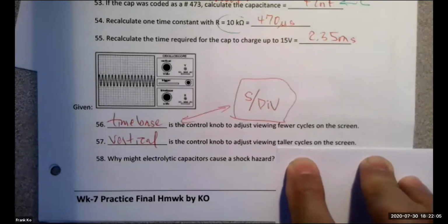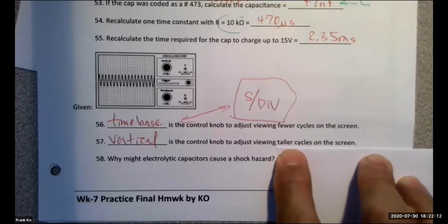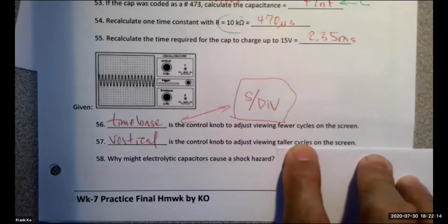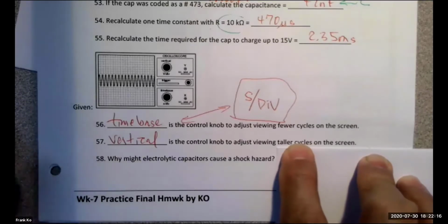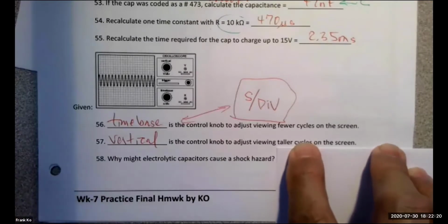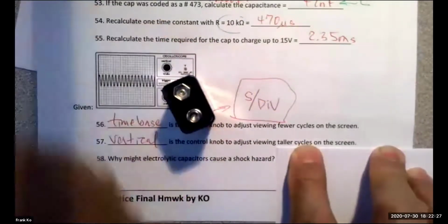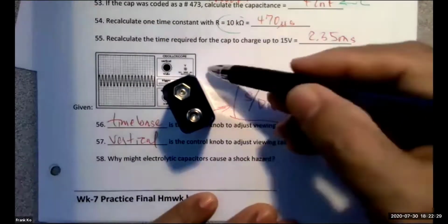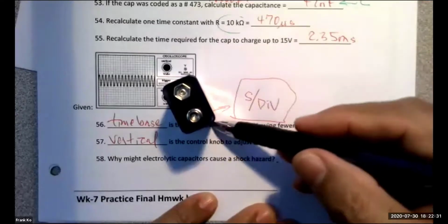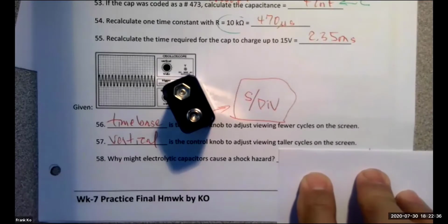It won't actively be oozing like lava, but it will have oozed out over time, such that when we look inside some of the larger audio amplifiers, at the circuit board upon which the capacitors are mounted, we may see some kind of corroded residue around the base of the cylinder of the cap. Imagine this is a cap sitting on the circuit board; we would see around its periphery some kind of corrosive-looking material, and that would be indicative of a capacitor that has leaked.